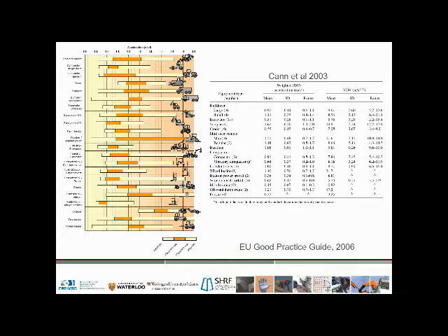We also observe to the right the levels of exposures experienced by operators of heavy equipment in the construction industry. The authors of this study found that more than 50% of 67 operators were exposed to levels of vibration that were above the standards of health risks. So the main takeaway from this slide is that whole body vibration exposure among heavy machinery operators in construction often exceed current guideline thresholds. And vibration exposure from different types of machinery in different industries generally fall within a range of vibration magnitudes.